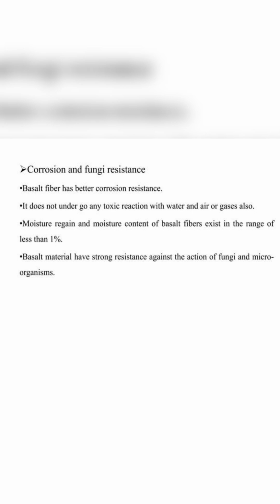The corrosion and fungi resistance: basalt fiber has better corrosion resistance and it does not undergo any toxic reaction with water and air or gases also. Moisture regain and moisture content of basalt fibers exist in the range of less than 1%. The basalt material has strong resistance against the action of fungi and microorganisms.